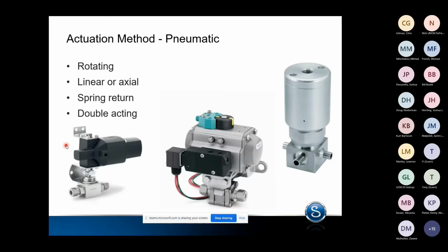That would be essentially if your facility lost power, lost pressure, what state does that valve return to? In a system failure, does it return to an open condition or a closed condition? So typically you want your vents to fail open and you want your processes to fail closed. It's a good question. Yes, you can configure them in either of those two orientations.